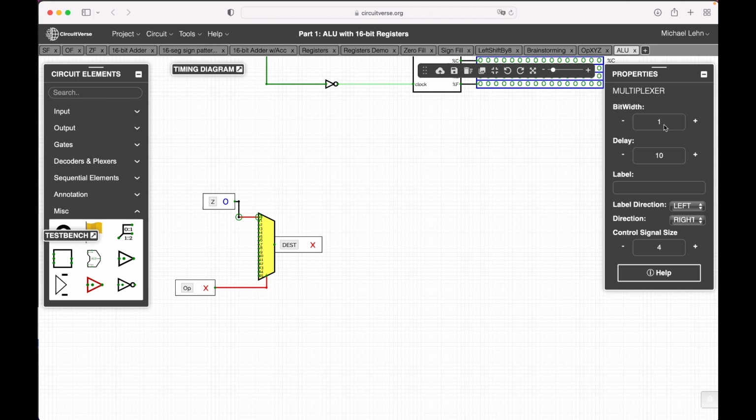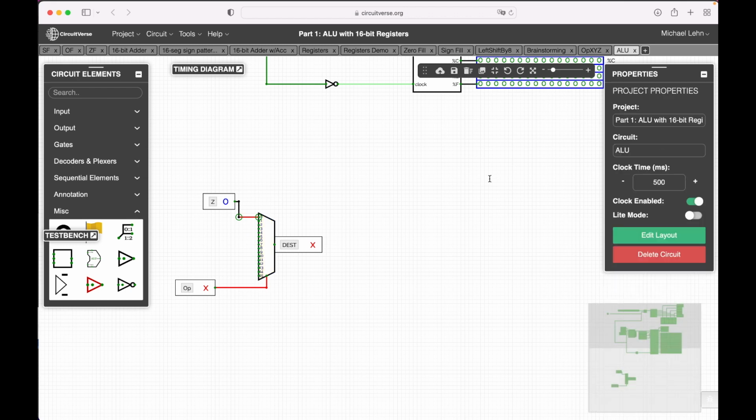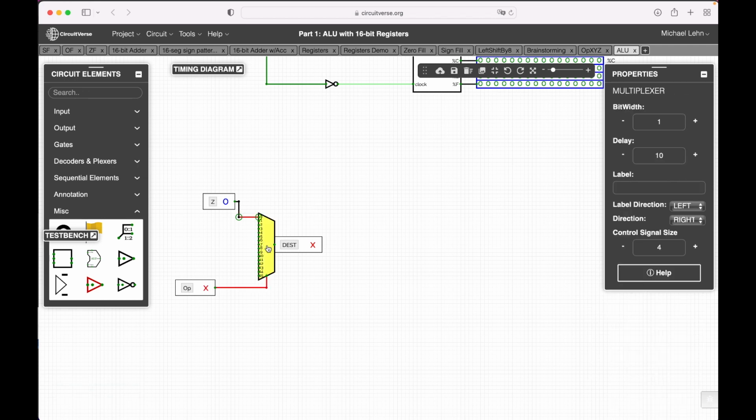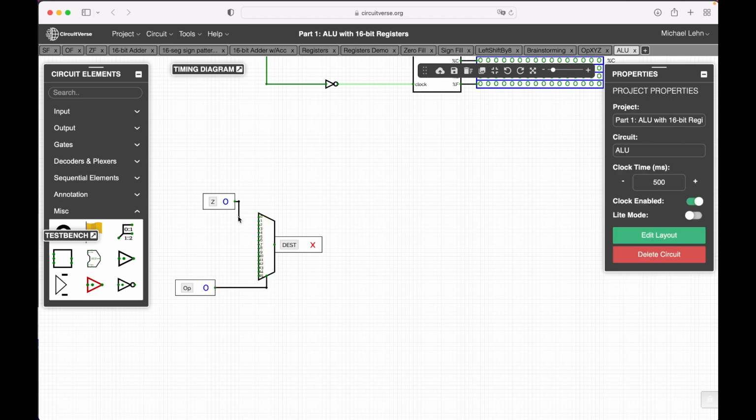And then you also should change here the bit size. And then sometimes you have to disconnect and reconnect so that Circuitverse sees that things are correct now. Somehow this didn't work. Change and return. Yeah, you might encounter similar problems, so I will not cut this out. Okay, and now I need this here, or something like this here, 4 more times.